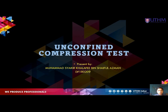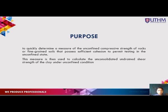Today I will present my project, which is the unconfined compression test. My part is the purpose of this test. The general purpose of this testing is to quickly determine a measure of the unconfined compression strength of rocks or fine-grained soils that possess sufficient cohesion to permit testing in the unconfined state. This measure is then used to calculate the undrained shear strength of the clay under unconfined condition.